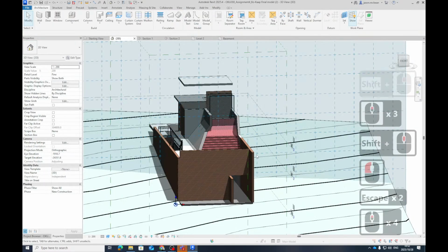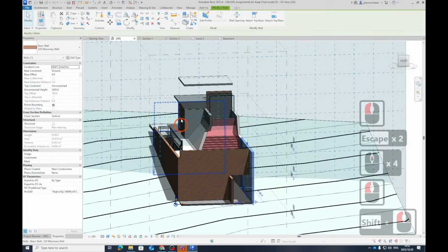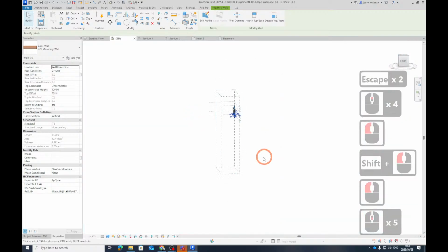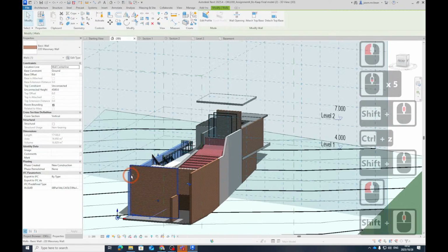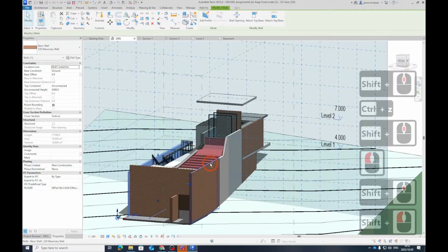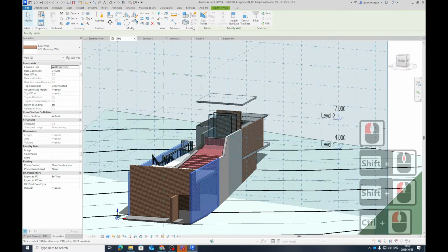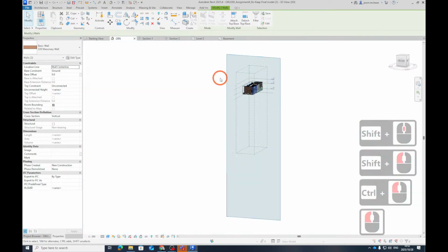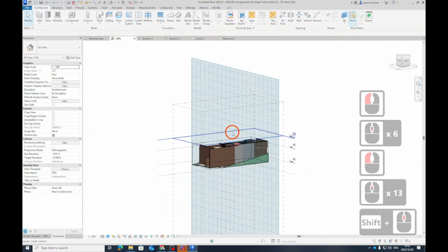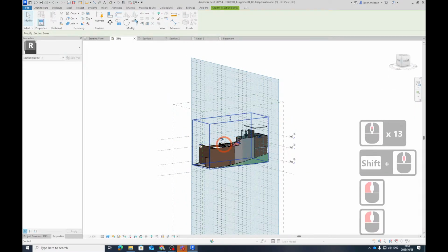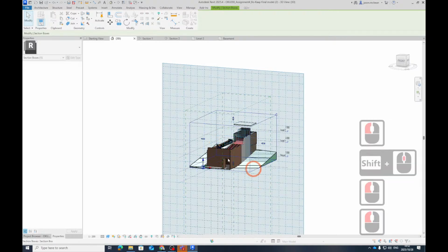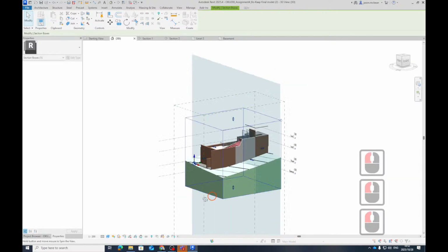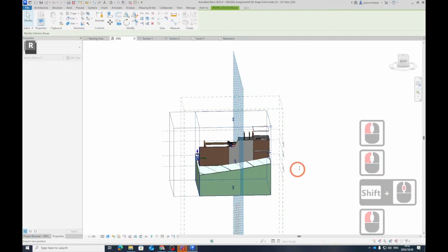So you can select this wall and that wall, and then use the section box tool again if you want to enable. Sorry, I should have selected. So that one and control down. I've been using Blender all morning. Sorry, it's shift. Section box. Now you can change your section box just to be around those objects, and then you can quickly fine tune it. But always duplicate a view. So if you've got enough information, select it, duplicate it, and save it separately. Okay. Thank you so much. And I'll save this and give it back to you.